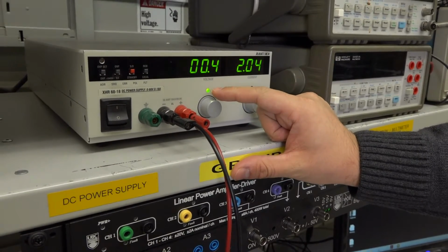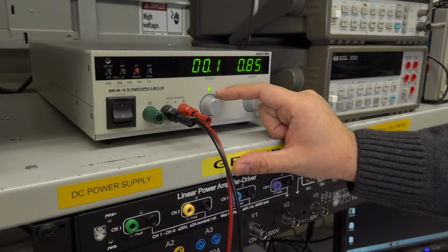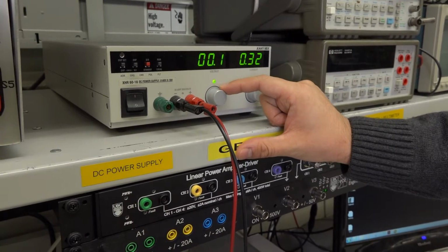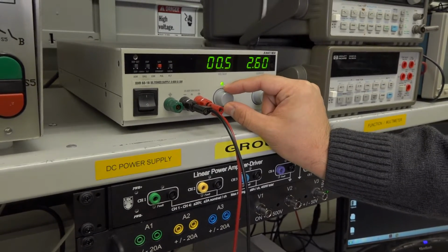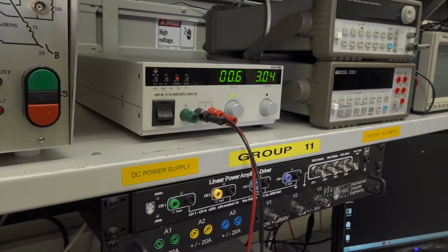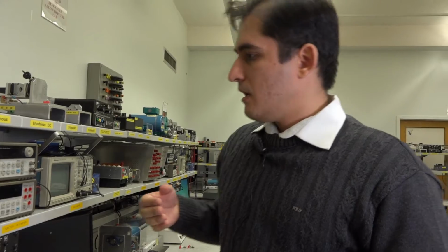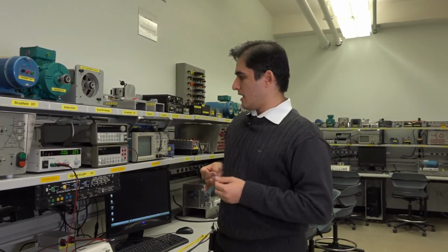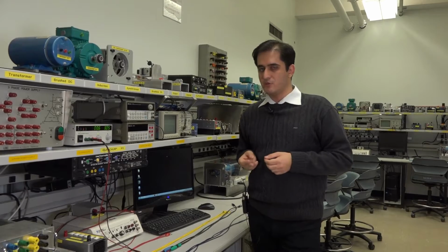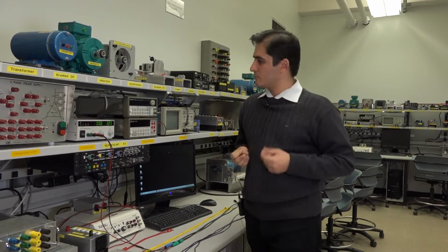You're going to have to measure the resistance at 3 different currents. I would say 1 amp, 2 amps, and 3 amps. You measure a resistance for each of the currents, and then you calculate the average of that resistance, and you can come up with the resistance that you are going to use as your final value. You will have to repeat the same procedure for the other side of the transformer, and that way you can measure the resistance for the other side of the transformer as well.